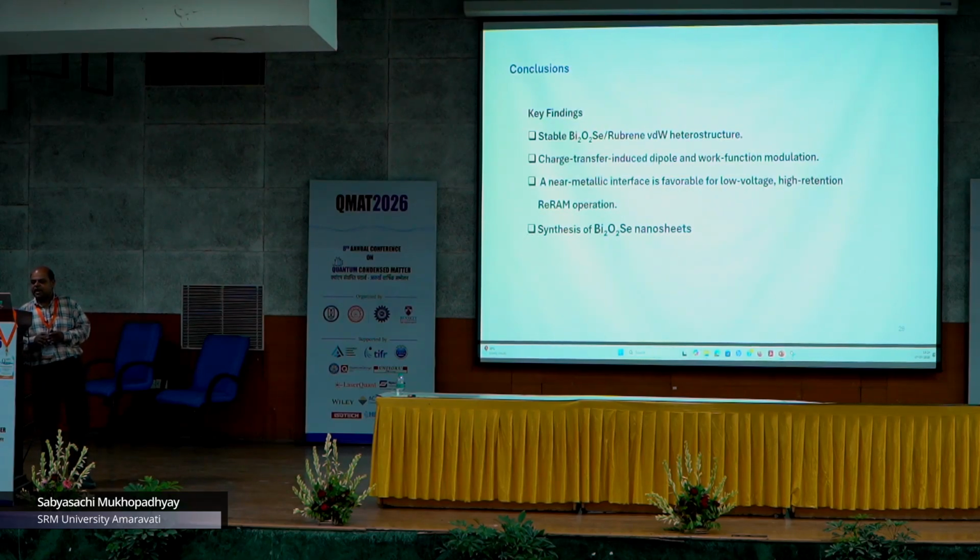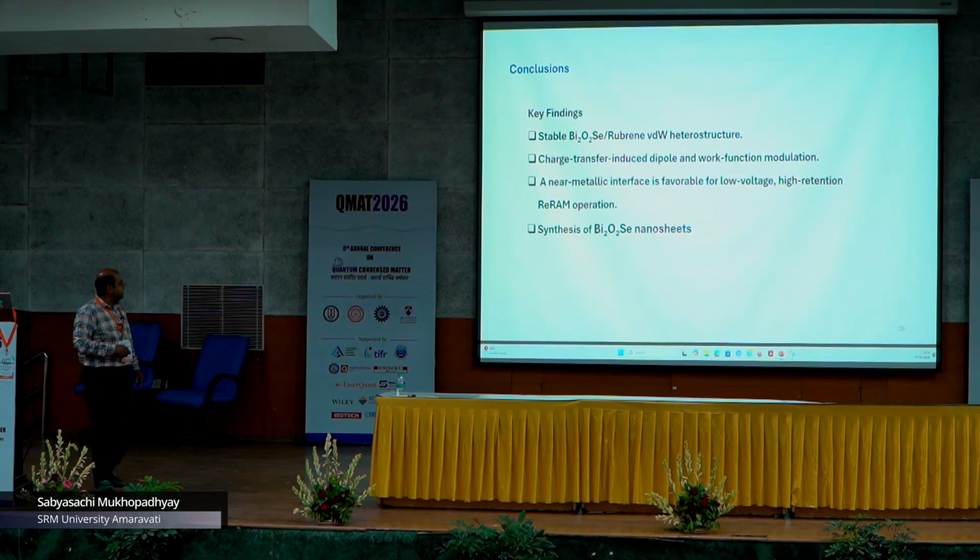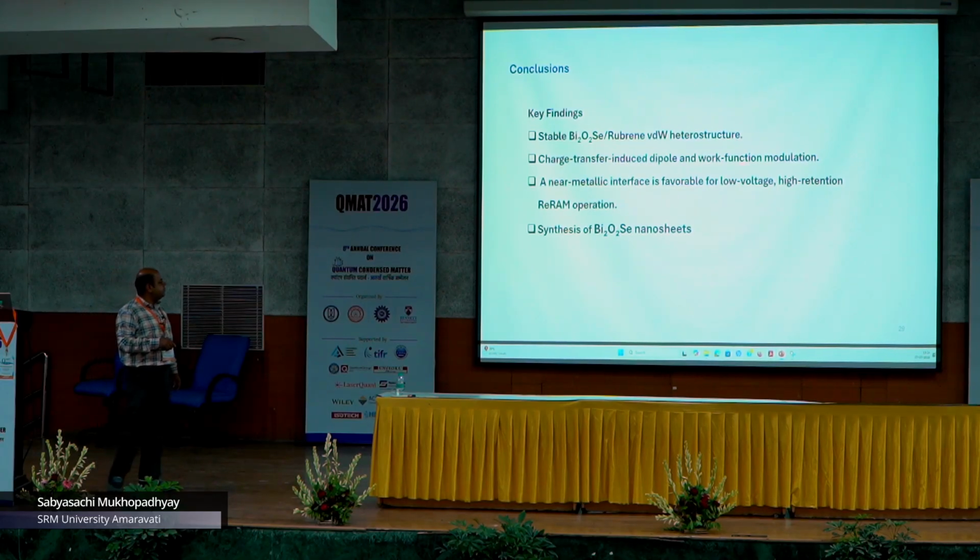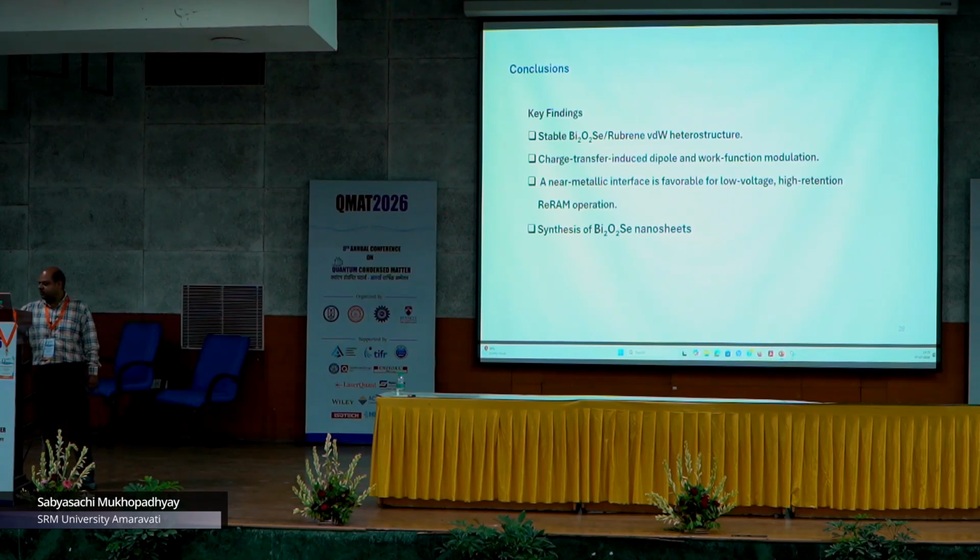Okay, so what are the key findings? From what we understood from our computational study, we have a van der Waals heterostructure with organic and inorganic materials. The charge transport induced dipole and the work function modulation at those interfaces, and the near metallic interfaces, we still need to understand the physics behind it, and it is going to help us with the low voltage and the high retention of the RAM operation. And then we have synthesized the nanosheets of these materials.